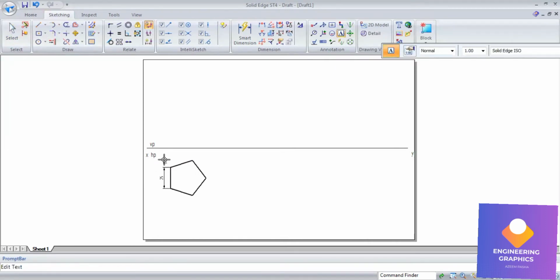You can write A, B, C, D, E. Okay, top face and bottom face. Top face A, bottom face A1 within bracket, because from the top view it's not visible. A, B, C, D, E is the top face notation. A1, B1, C1, D1, E1 is the bottom face notation, and these bottom face notations are not visible from the top view. Okay, and the centers of the axis are O and O1, with O1 within bracket.